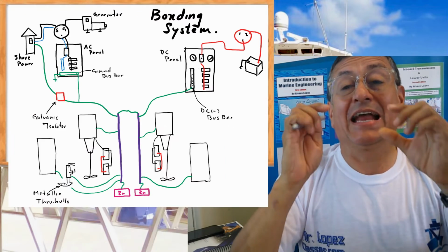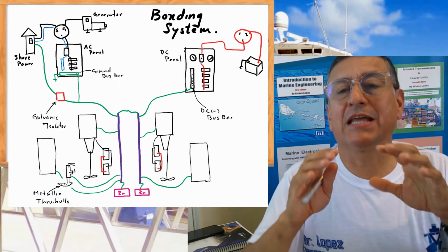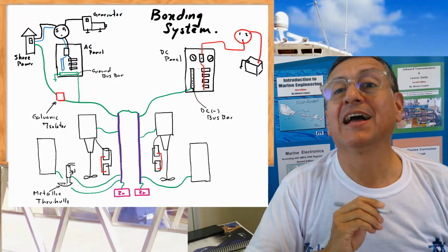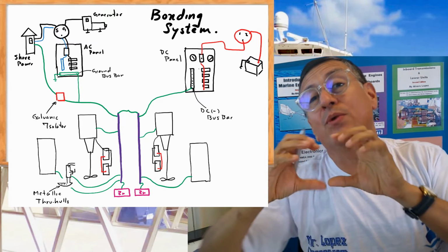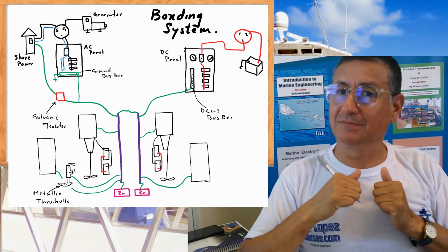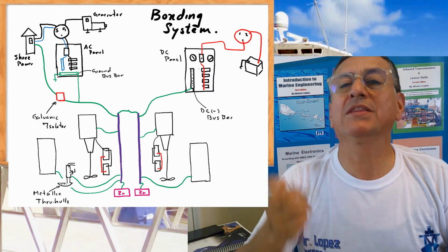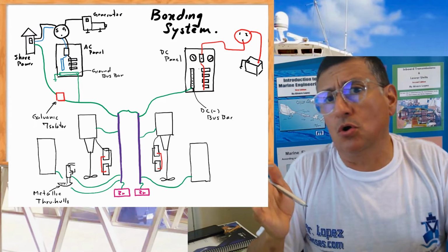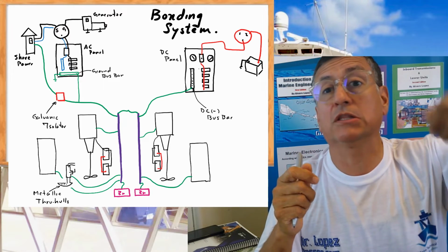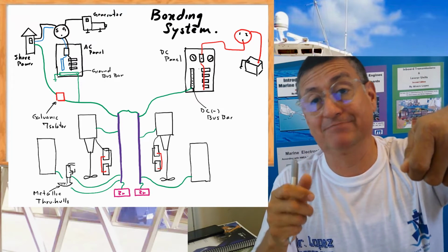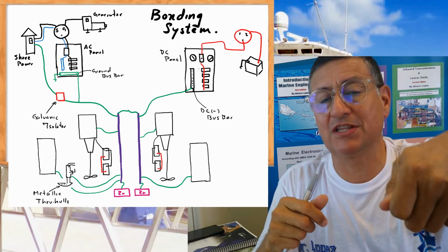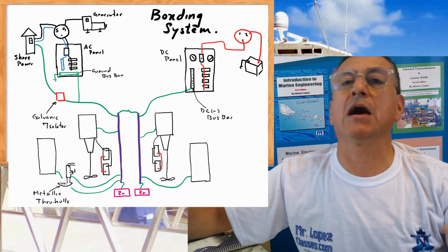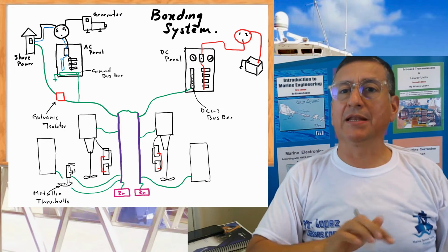Okay. The grounding conductor, the green cable, is the cable that connects the case of the equipment with the bonding conductor, and the bonding conductor is connected with a cable to the sinks, with the ground outside. Alright, now it's clear. What is the function of that green cable? Drain static electricity. Or, in some cases, if you have a short and the hot line touches the case, or the positive touches the case, it is DC, that green cable drains that current quickly into the ground. The function is to drain to the grounding.